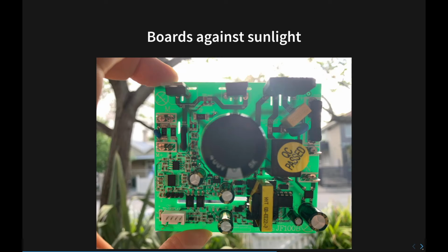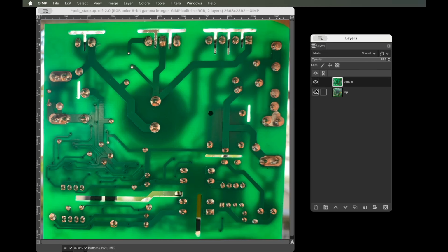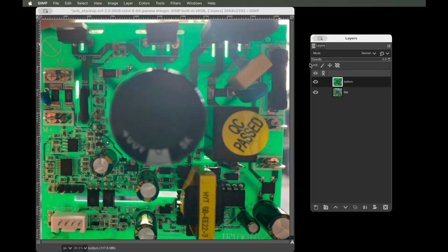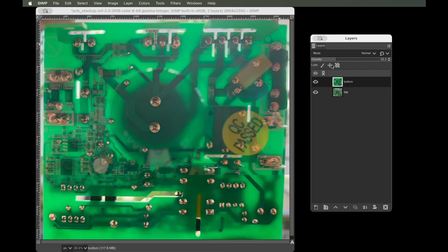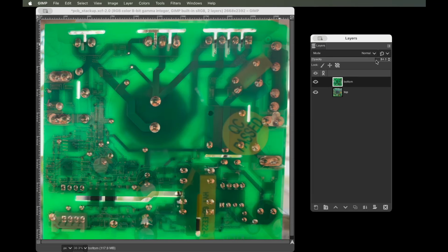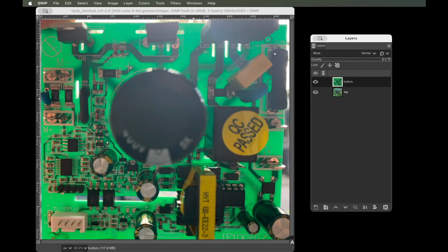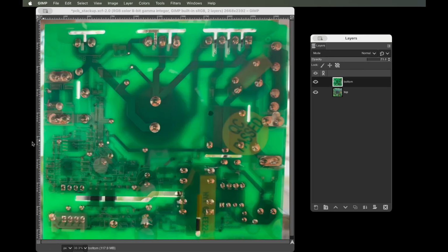Let me explain what this means. So look, it's really simple. You just have two pictures of the PCB, one on top and the other at the bottom. And then you have this opacity slider. And then you can see when you superpose them correctly, with the correct solutions, as we will see later, you can easily trace where, for instance, different vias go. Like, let's say we want to trace this one.